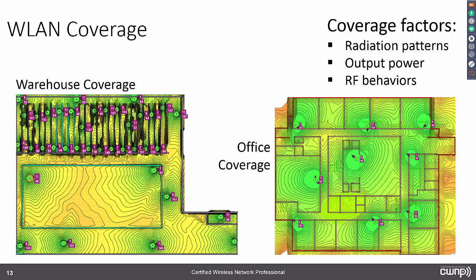But we can see already a very different radiation pattern in this real world space than what you have in just open spaces. Or let's say it this way, what your antenna charts tell you the radiation is going to be. All that antenna chart tells you is the initial way in which the RF energy is radiated out of the antenna. They cannot tell you how that RF energy is going to propagate through your environment.